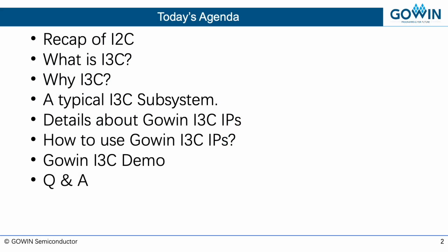Let's move along. Before we dig deeper into the I3C interface details, let me tell you what I3C is and how it is related to the decades-old I2C interface, or I-squared-C interface as we know it. The I3C interface incorporates key attributes of the traditional I2C and SPI interfaces to provide a unified, high-performing, very low-power solution. It also delivers a robust, flexible upgrade path for I2C and SPI implementers to I3C.